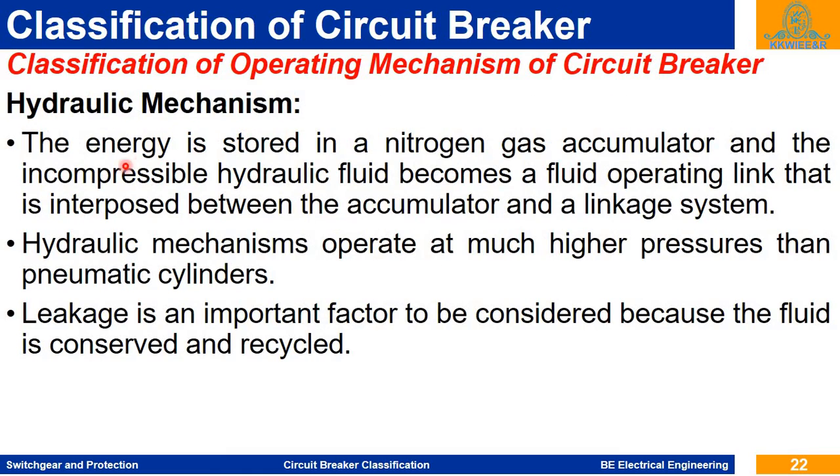Next is the hydraulic mechanism. The energy is stored in a nitrogen gas accumulator, and incompressible hydraulic fluid becomes a fluid operating link that is interposed between the accumulator and a linkage system. Similar to the pneumatic cylinder, here a hydraulic piston or hydraulic cylinder is there.